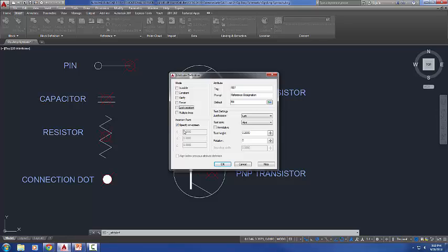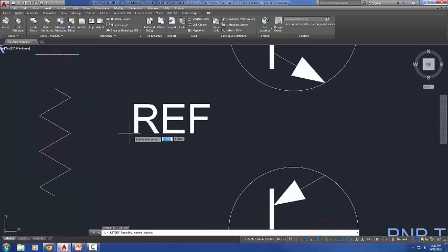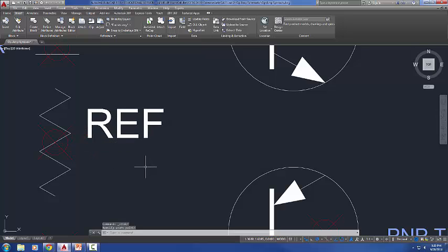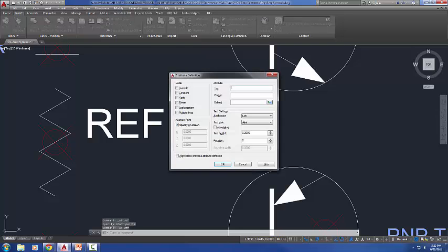And what that allows it to do is show the layer state that I need without affecting all of the other viewports. So again, you cannot choose from this list. I understand why you want to. It's natural to want to choose it from this list, but this list is messed up when you're in your viewports. You have to go to Manage Layer States, select it from this list, and say Restore. And that's the only way that you're going to be able to get your layer state to show in that viewport without affecting other viewports.